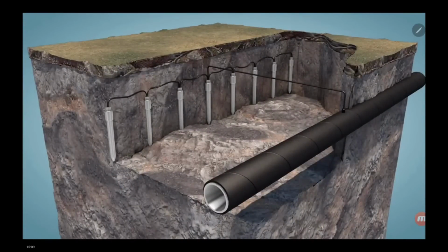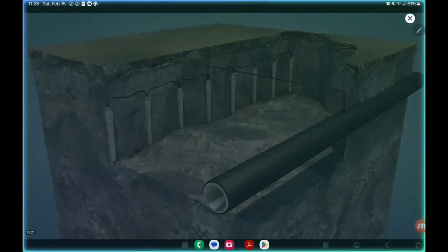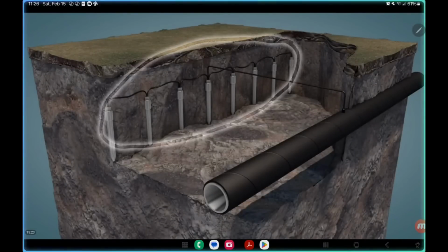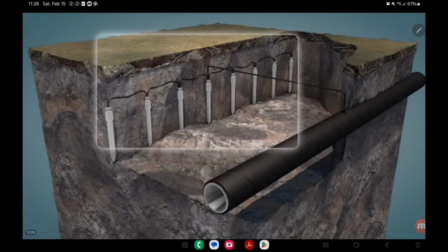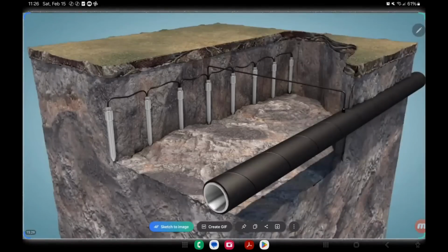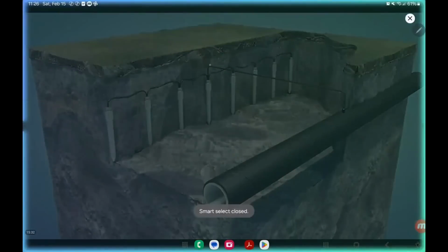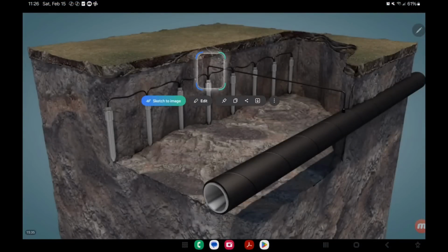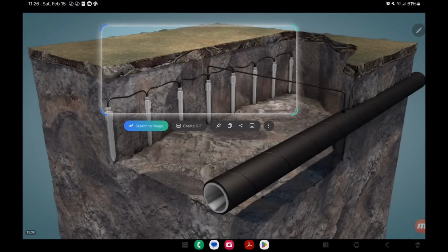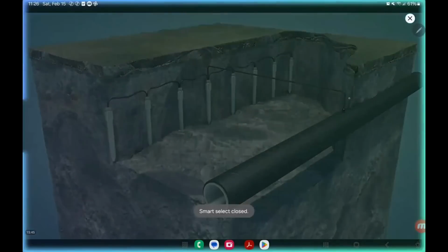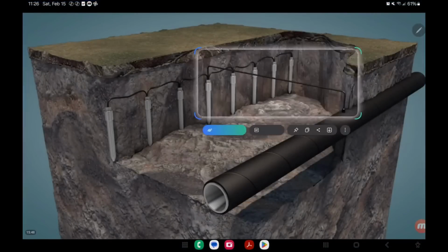This is another configuration of sacrificial anodes, and notice that they are connected vertically but parallel to the pipeline. And as you can see, gentlemen, a common point. Which is the common point? The common point is this one here. Sorry if I sometimes get tangled up with this. The common point is this one, but then all the other anodes are interconnected. And we have the connecting cable, the cable that links the pipeline with the group of anodes. So this is the other type of configuration.